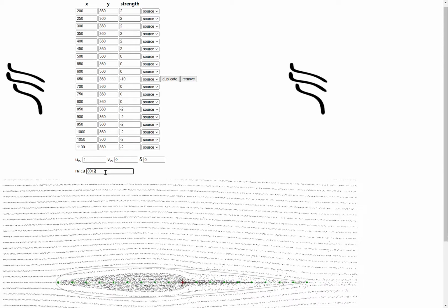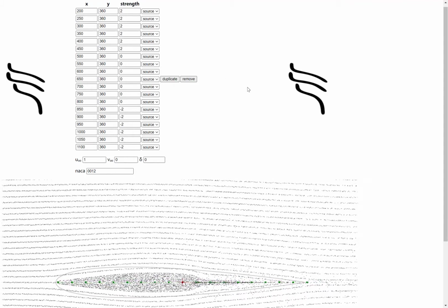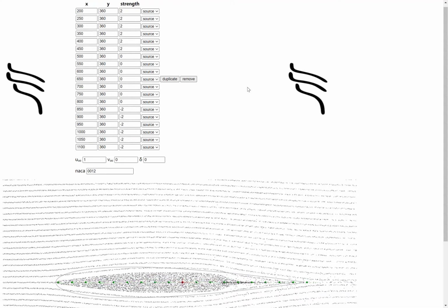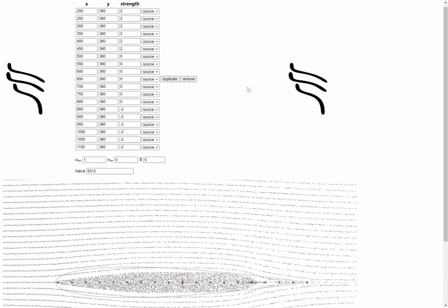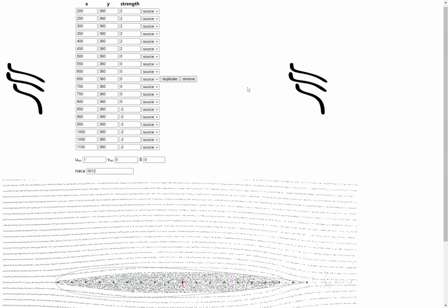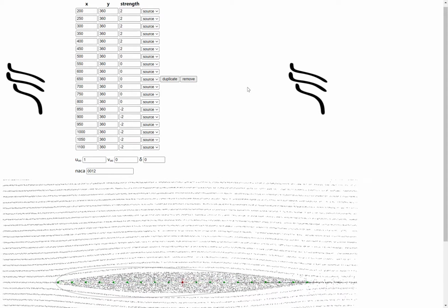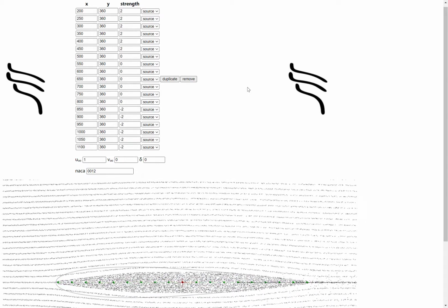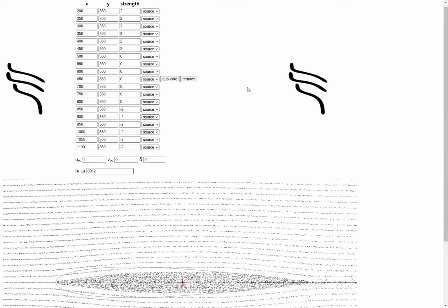If the airfoil thickens very rapidly, we put a large source; if it thickens very gently, a smaller source. If it thins out very fast, we put a larger sink; if it thins out slightly, a smaller sink. It doesn't have to be perfect.